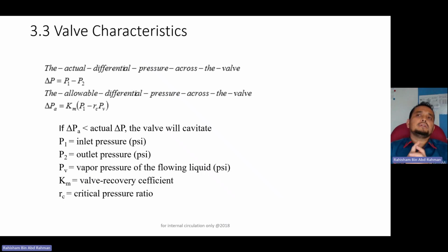Okay, we understand about the cavitation. We understand about flashing, how it happened. So it's happened purely because of the pressure difference. A quick recap: pressure difference between before and after the opening, after the valve.